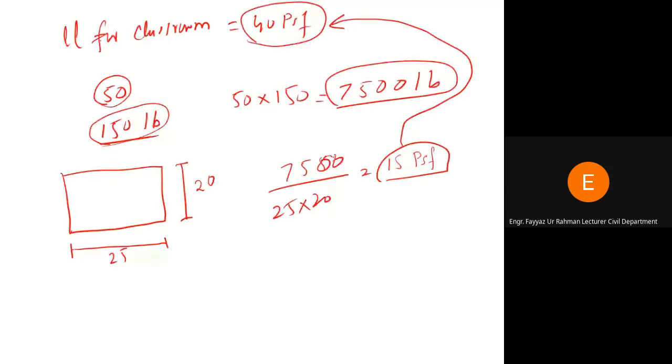Why? Because they are not deterministic. You cannot determine the live loads with high degree of accuracy. You can determine these values only probabilistically. Clear? And since there is chance of high variation in the live load, therefore the load factor for live load is 1.6. So we will also multiply live load with this factor 1.6 for the design.